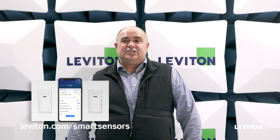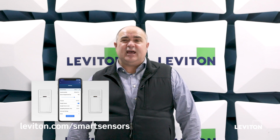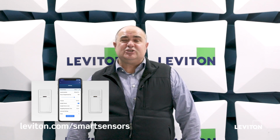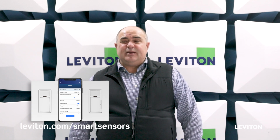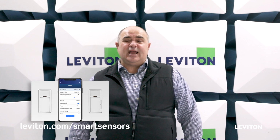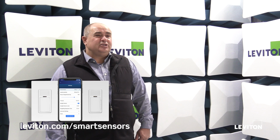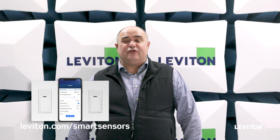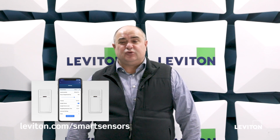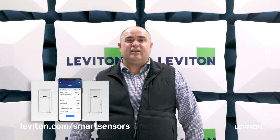When you get up into some of the larger areas, you might have some challenges with some of the corners and things like that. But for the most part, this sensor is going to meet all of the requirements for smaller areas. And again, as I mentioned, the lens itself is now a tamper-resistant passive infrared lens, and the new multi-tech technologies are currently using the microphonic technology. As I mentioned, we can now add a power pack for controlled receptacle or plug load control with our 24 volt versions of either the passive infrared or the multi-tech solution.